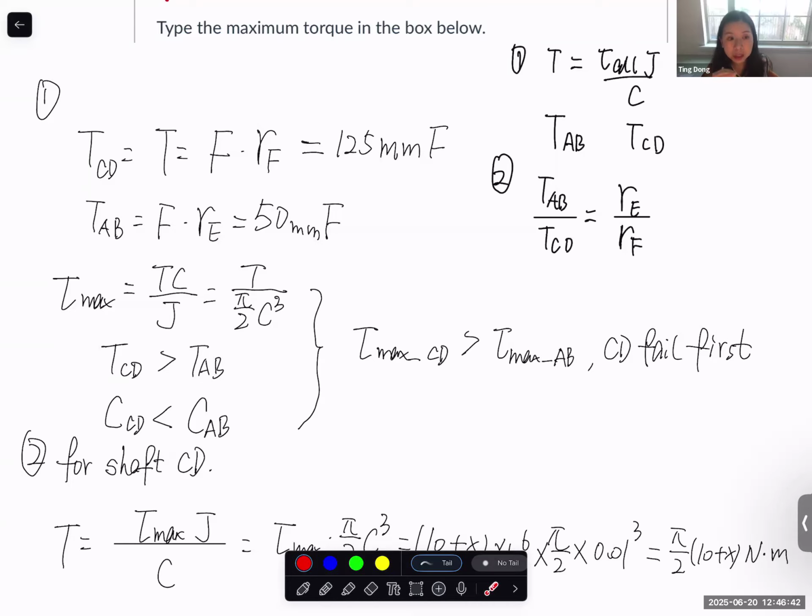Make sense or not? The gear ratio only proves that torque is larger. It does not prove that shear stress is larger. For comparing the shear stress, you need to compare the torque and radius. Just one of them is not enough.